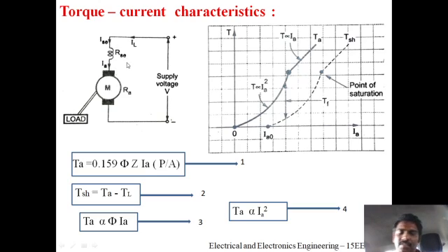In case of shunt motor, if you recall, the field winding was coming in parallel with the armature circuit. But here, the field winding comes in series with the armature circuit. Therefore, it is called as DC series motor. If you observe the terms of current, IL represents the line current or load current, which comes from supply.